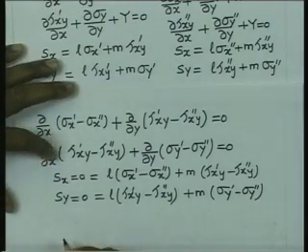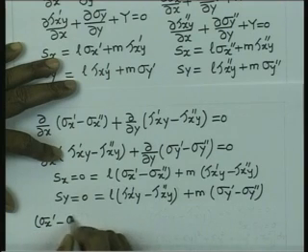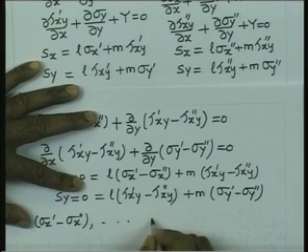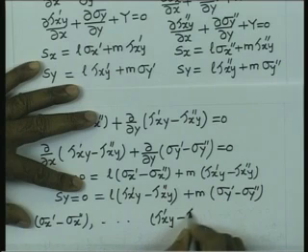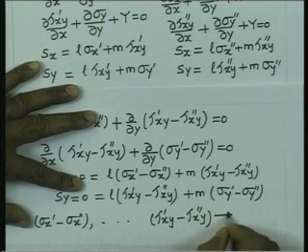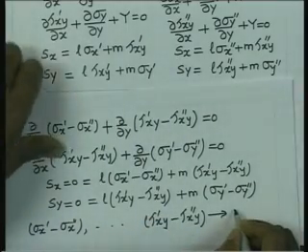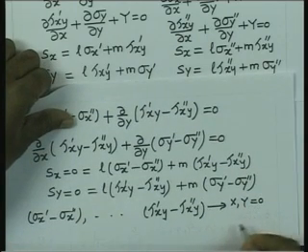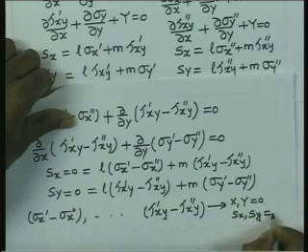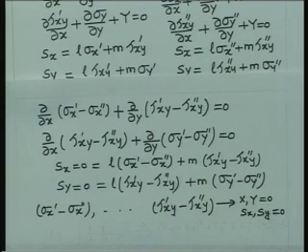So, we find that this set, sigma x dash minus sigma x double dash, similarly tau xy dash minus tau xy double dash, corresponds to a set of loading wherein X, Y are 0, and so also Sx, Sy are 0. So, the new set involving sigma x dash minus sigma x double dash, sigma y dash minus sigma y double dash and tau xy dash minus tau xy double dash corresponds to a set of forces wherein the body forces are 0 and also boundary forces are 0.